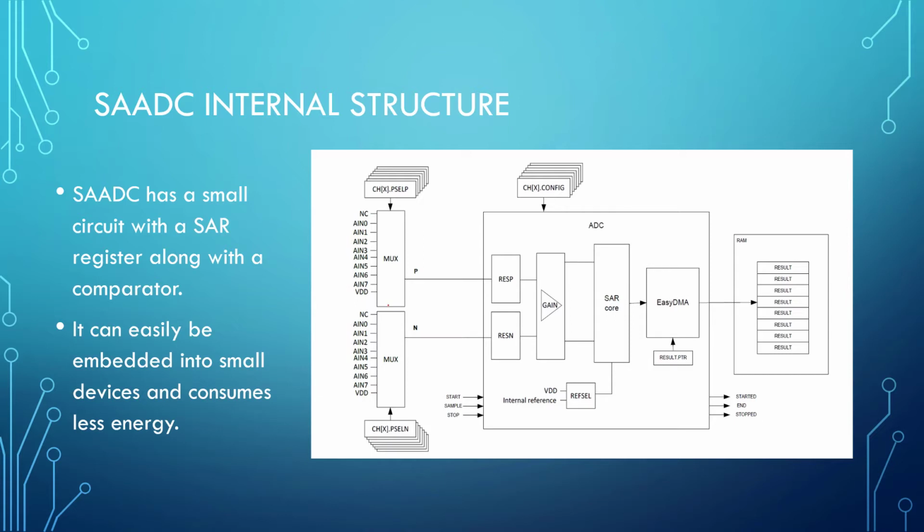The digital pins that we use in our nRF devices can be allocated to any pin, any output pin, but when it comes to ADC, we have to look at some specific pins, and we will see what pins are there for us to communicate with the ADC module.